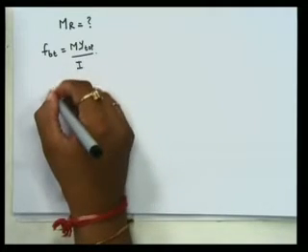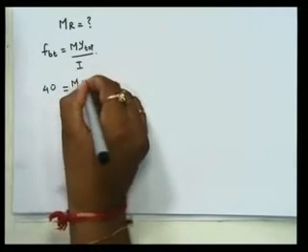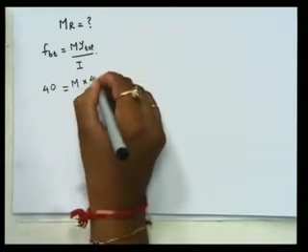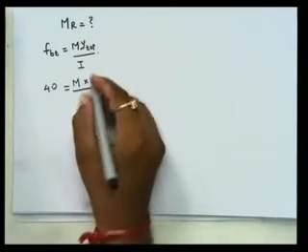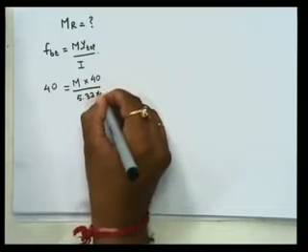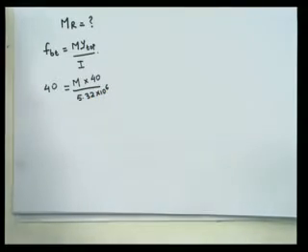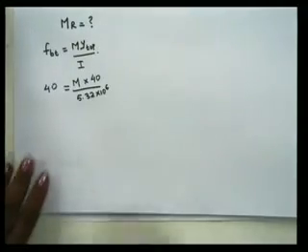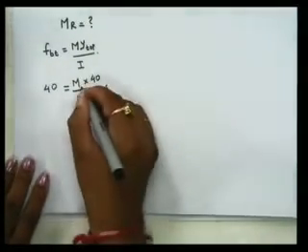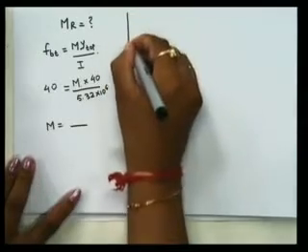FBT, they have given as 40, is equal to m into y top, that is 40 divided by I, that is 5.32 into 10 to the power 6. Okay, so we can get the value of m. Okay, similarly